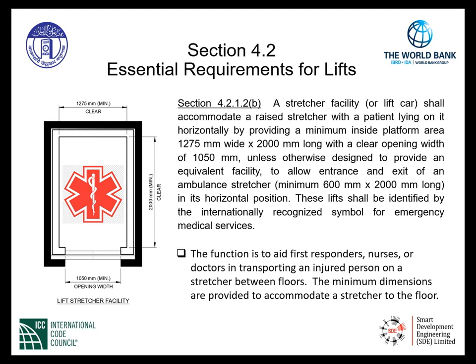As you can see, the minimum of the ambulance stretcher is 600 millimeters by 2,000 millimeters long. These lifts shall be identified by the internationally recognized symbol for emergency medical services. As indicated in the graphic, we can see the minimum interior dimensions that must be maintained when a stretcher facility is required for the lift car. The function is to, of course, aid first responders, nurses, or doctors in transporting an injured person on a stretcher between floors. The minimum dimensions are provided to accommodate a stretcher to the floor.